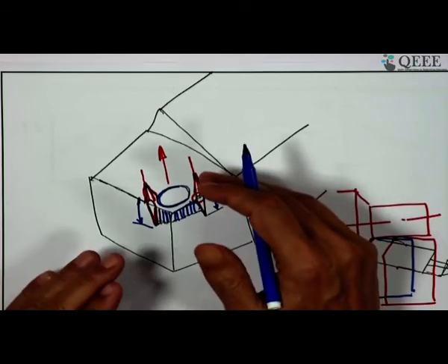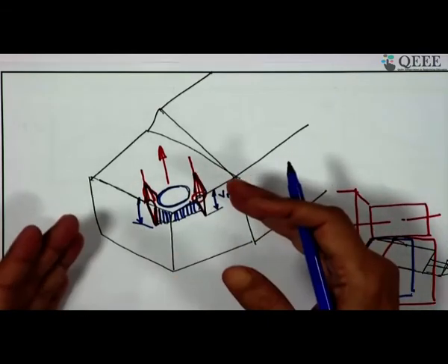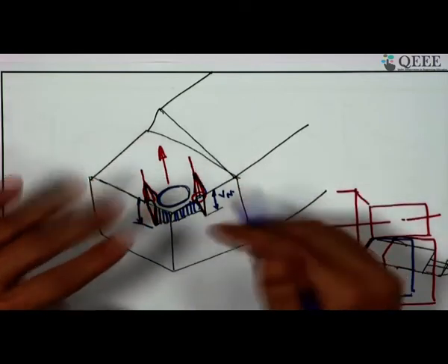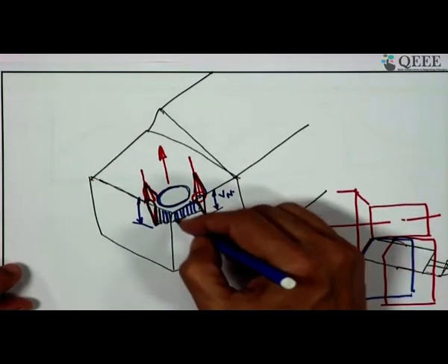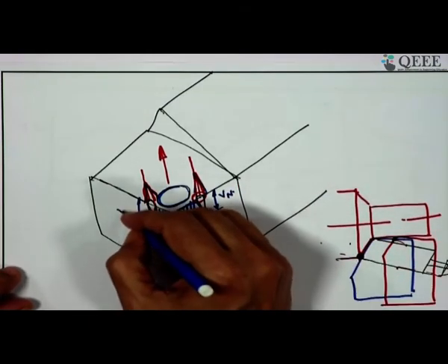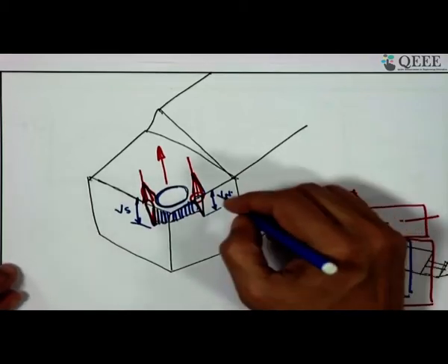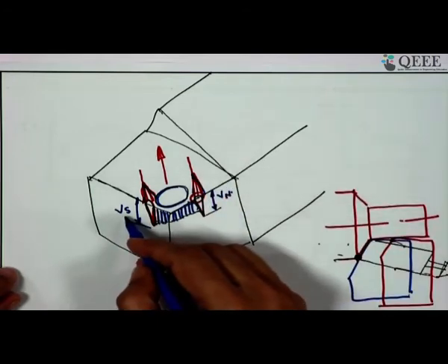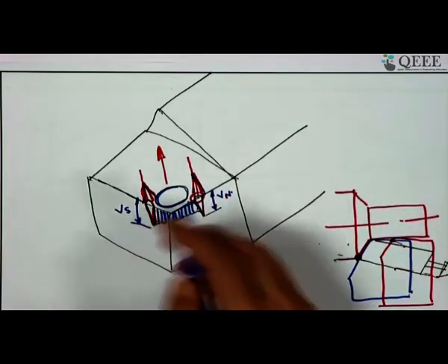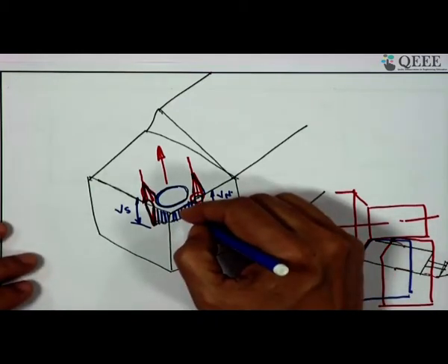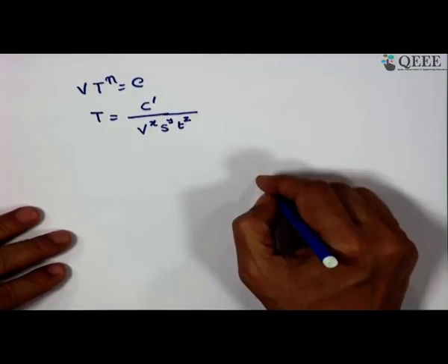As I have just mentioned, you put it under the microscope, against the eyepiece, and you see the entire wear pattern on the objective, and you can measure the dimension at different positions. This is called V s. So, V n is the width of notch on the principal flank, V s is the width of notch at the auxiliary flank, and what is V b? V b is actually the average flank wear.